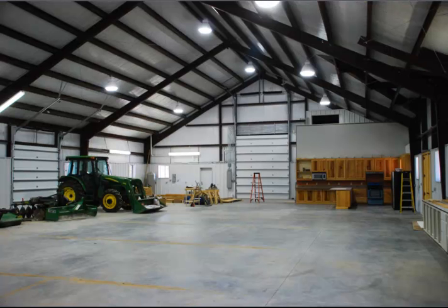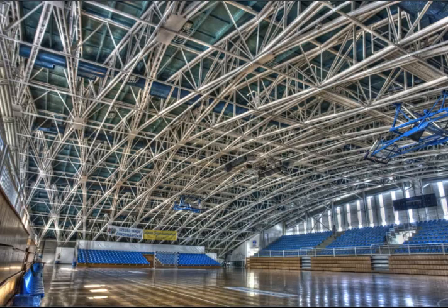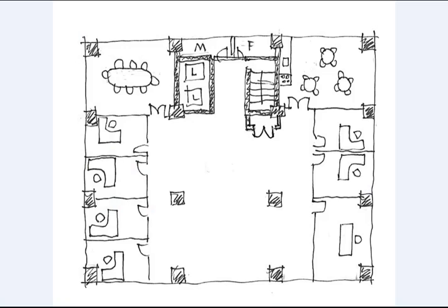We've got a storage facility here, pretty much a warehouse construction, and what we're using here is structural steel. It's quite often the common material used because it's lightweight and it offers us very large spans. Here's an interesting example of a space frame for a gym. Very large footprint and probably only 1 or 2 levels in a building of this type.